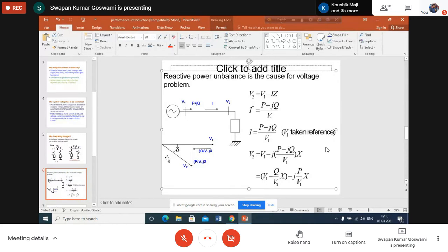Obviously, as you have mentioned, why we are not including that? Obviously, capacitors have some role to play in the voltage control of the system, by supplying reactive power. So they help the system to maintain voltage. But in this analysis, we are not taking that into consideration. We are assuming that capacitors are there, they will be supplying. But what is happening due to the variation in load current? Because of the variation in load current, there is voltage drop occurring in the system, and that voltage is dropping because of mostly the reactive power requirement.